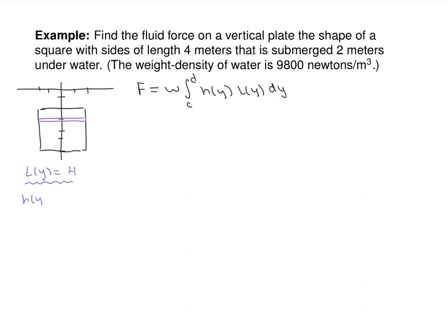Now we need to find h of y. Remember, that's your depth. And before we do that, it is best to talk about what the bounds on that integral are going to be. And also we can plug in 9,800 newtons per meter cubed for that W.